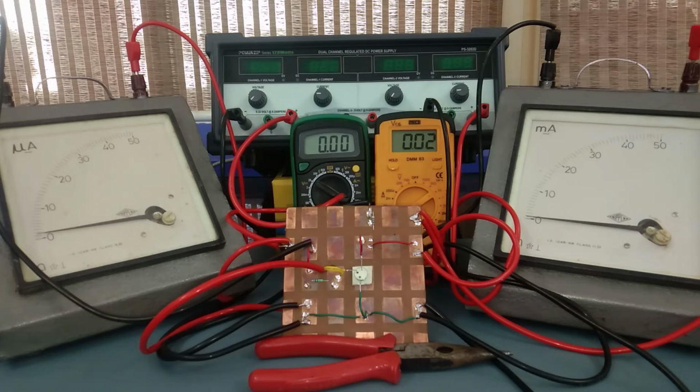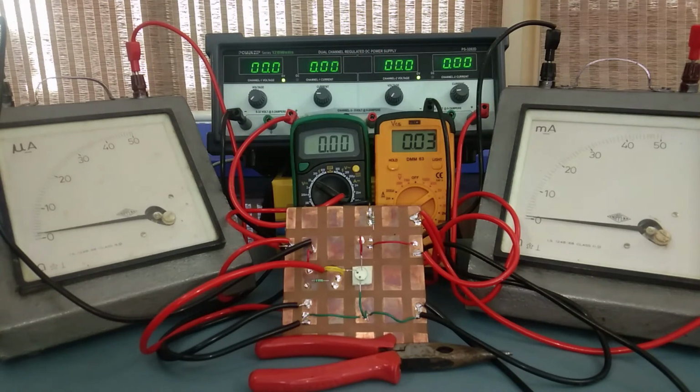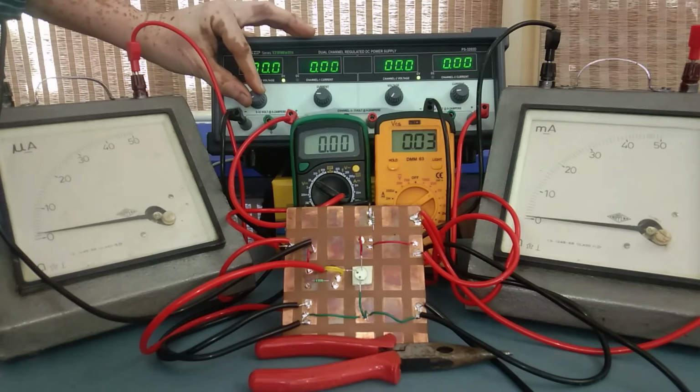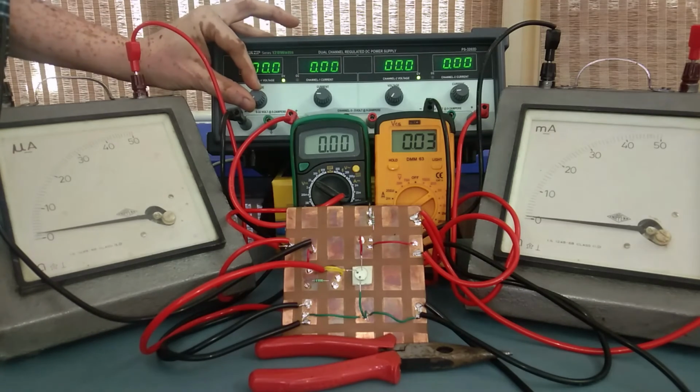Now let us start taking the readings. I will not take each and every reading, I will show you only the trend. When you actually perform the practical, then you take the readings cautiously. Now I will put on the power supply. Initially we will be studying the input characteristics. So the VCE will be at 0 and we will be changing the VBB. You can see here, I will slowly make the changes.